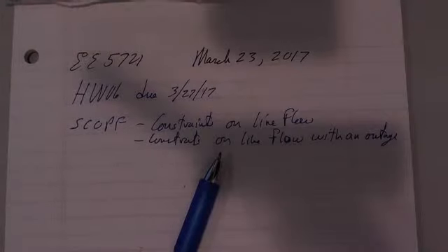In other words, I'm going to set the system up sort of pre-arming it so that if there's an outage, nothing overloads. Now remember, that's the NERC N-1 criteria, that no line will overload on a single outage.